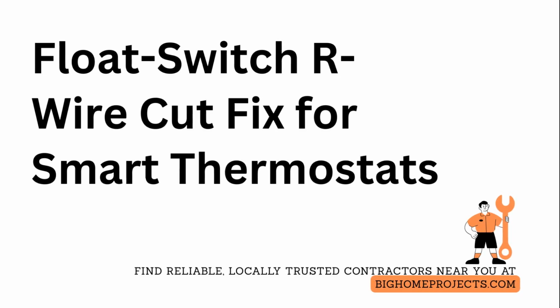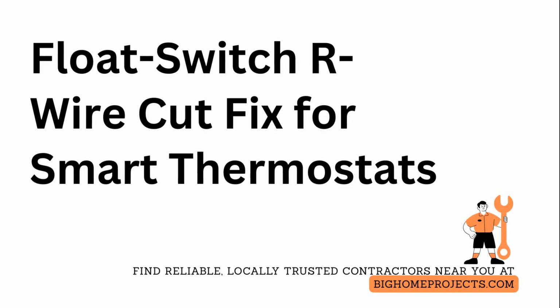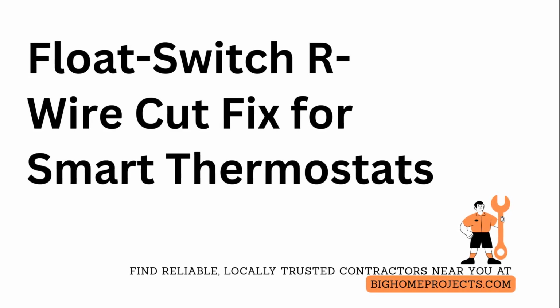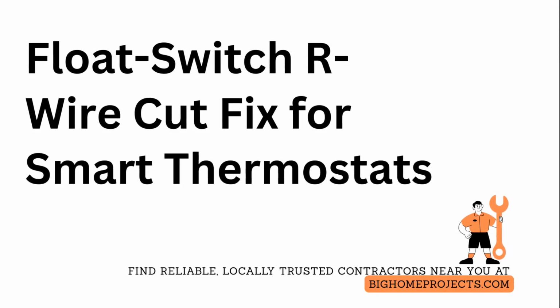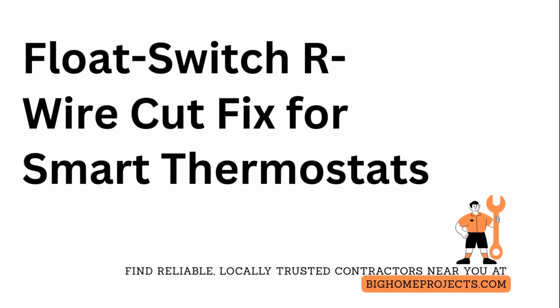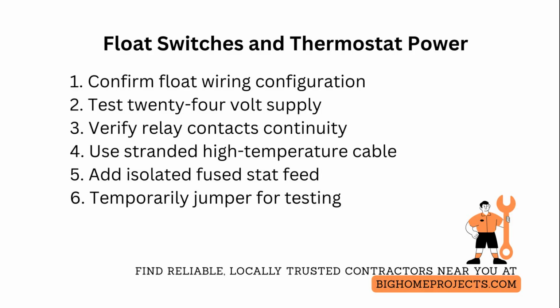Float switch trips can cut power to the thermostat and make a perfectly good heating, ventilation, and air conditioning control look dead. So learn exactly how float switches interact with the R wire and how to diagnose and fix it fast. Float switches sit in the condensate drain pan and open the R wire circuit when water rises.